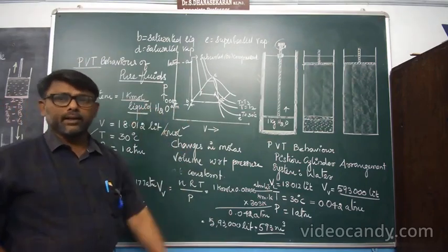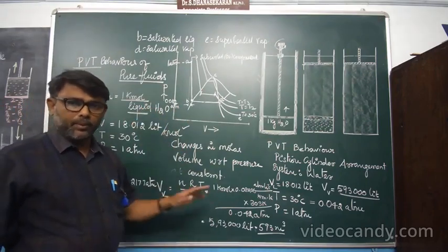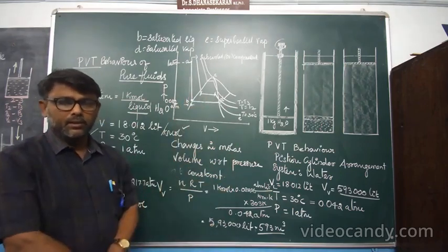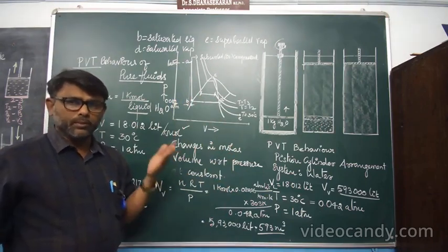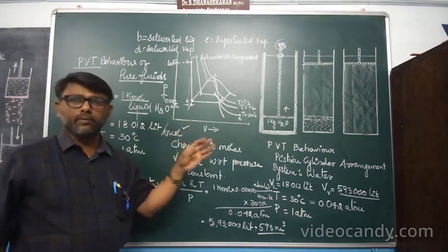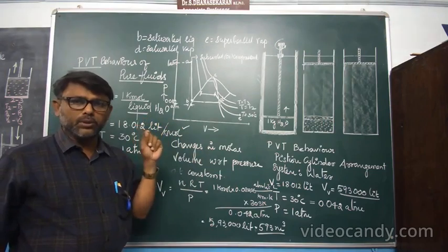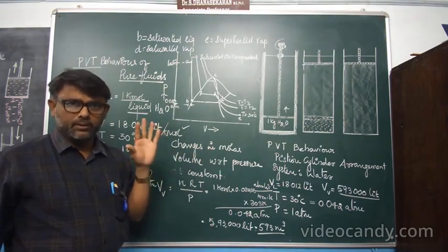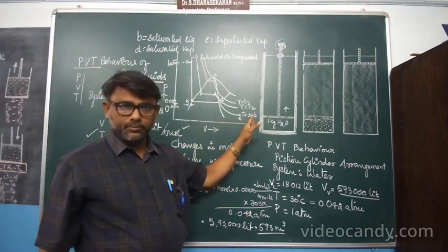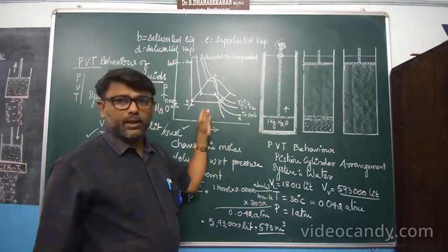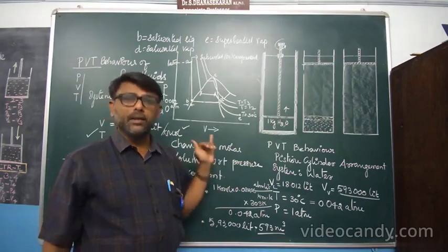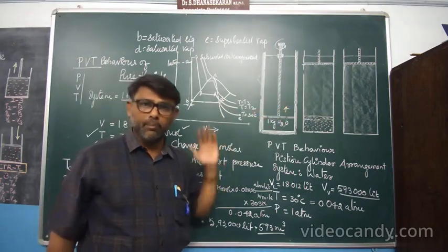If temperature and pressure are beyond the critical temperature and critical pressure, there is no distinction between vapor and liquid. No one can say this is saturated liquid, this is saturated vapor. It is not possible to distinguish vapor from liquid. Okay. Above the critical conditions, the vapor cannot be converted into liquid by either method, or the liquid cannot be vaporized by any means.